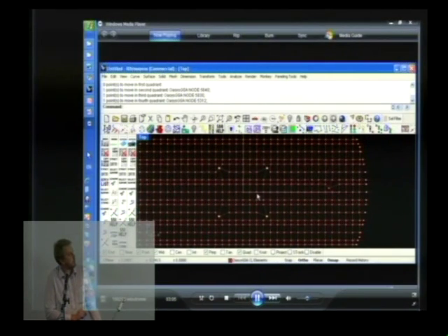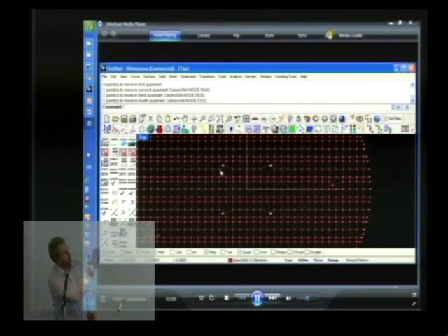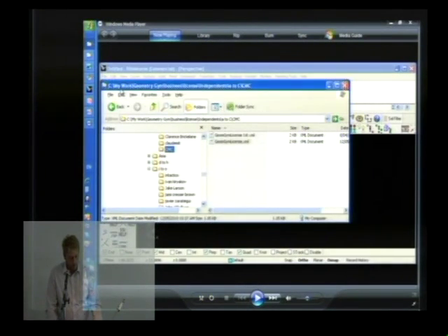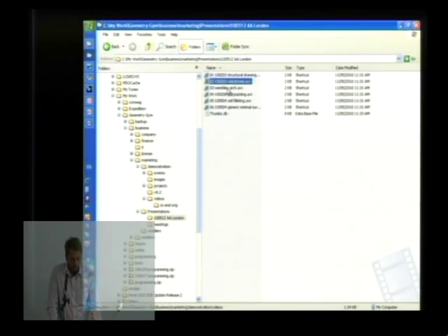The velodrome was not a mathematical setout, but it did have symmetry in that the quadrants effectively mirrored round the stadium. So rather than make a change in one quadrant and then have to repeat it in the other three quadrants, again, repetitive work with the risk of an error, or not having the exact changes made in every quadrant, I wrote a little tool in Rhino for watching for symmetry. So you turn that on. If you move a node in one quadrant, it checks to see if there's any point in the other three quadrants within tolerance of that point, and adjusts it accordingly. So it allows you to streamline and do your work a little bit more effectively.